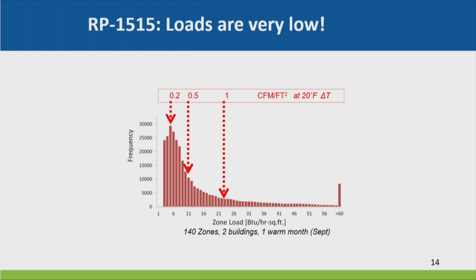So we did a research project to test it, and we did 8 campus buildings for Yahoo, and then another state office building, and we changed the sequence where we went from 30% minimums, which is the Title 24 number at the time, conventional logic, and then we'd flip it to dual max logic, and we did it randomly over an entire year. And after it would switch, maybe the day after or something like that, it would pop up these little screen things to people who volunteered for it, which was almost everybody.